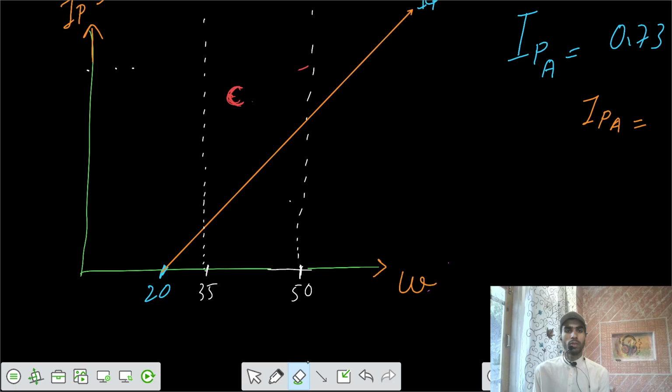Why intermediate compressible? Because your liquid limit is in the range 35 to 50%. And if your soil is somewhere here below the A line, but in the same range, we can say that this is silt. The soil is silt, and its compressibility is in the intermediate condition. So we can write this as MI.